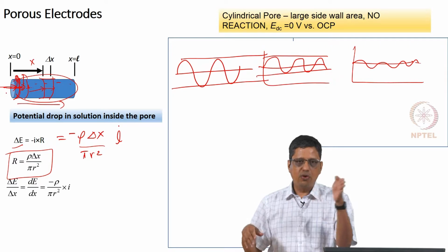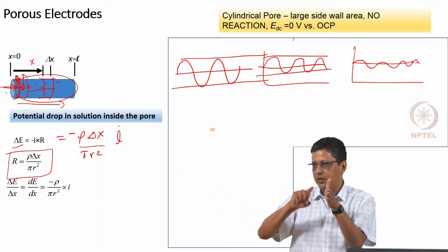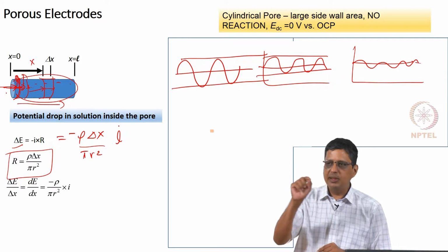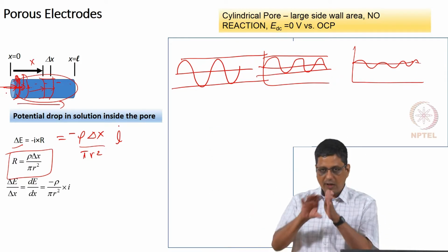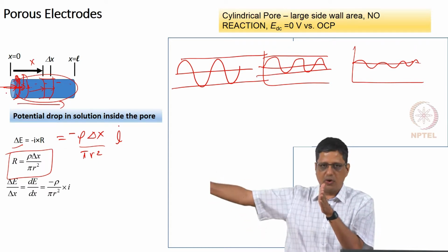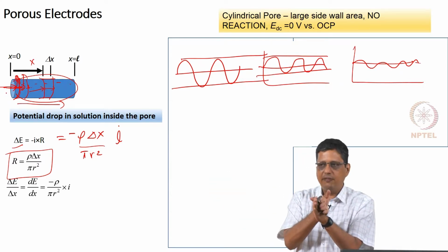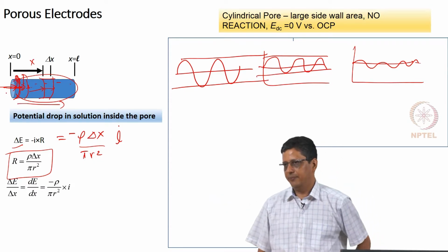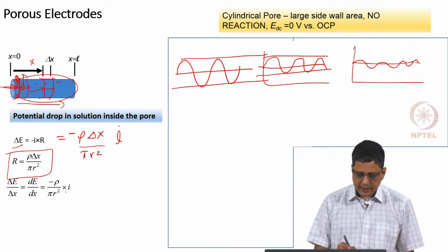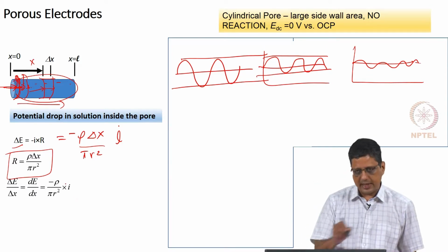The total fluid flow rate here under steady state condition should be equal to the integral or sum of the fluid flow rates at all these sections. This assumes the holes are of similar size. I will not get an even flow out of this along the length. I will get a higher flow rate in the beginning and a lower flow rate at the outlet, but the net flow rate here is enough to tell the total flow rate. So, at any location, this I is equivalent to the flow rate at that location. Of course, it is going to depend on x.